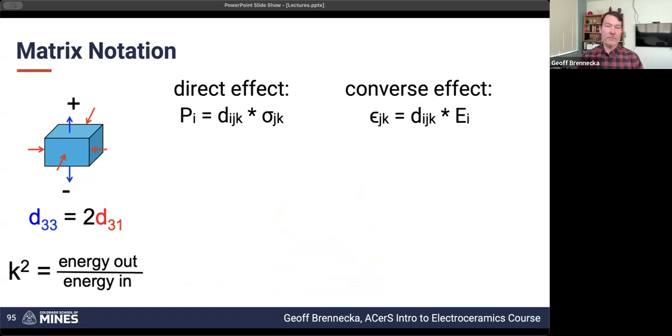So that's hopefully not too terribly confusing, but it's also not necessarily transparent when you're looking at spec sheets or when you're buying these materials or making these materials or making the measurements. So I wanted to spend a little more time clarifying that a high K squared is referring to the conversion between electrical and mechanical. It is independent of the actual tan delta, the amount of dissipated loss, where the energy is just being lost and going into thermal.